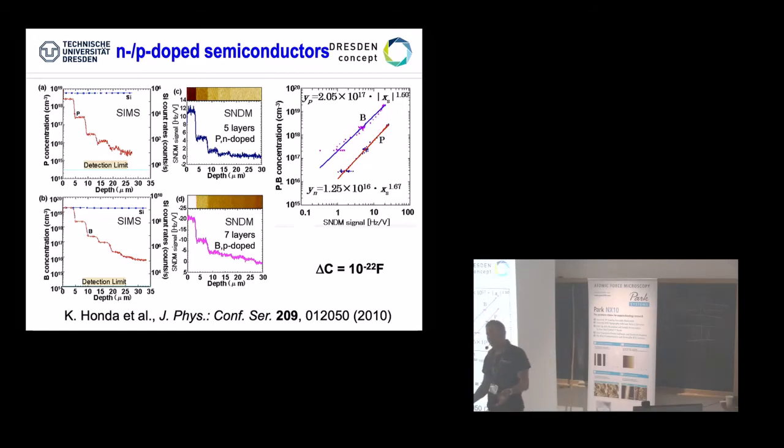Or if you want to put it, you can also measure with this the concentration of any kind of defects in this system. You see the sensitivity is typically different for P and N doped, typically 10 to the power 17 to 10 to the power 19, where for negatively doped, it's even better. Okay, you can say, well, a certain regime, not too much. There are tons of drawbacks. The resolution is not too bad because the capacitance measurements can be really very low. But there's one big drawback.